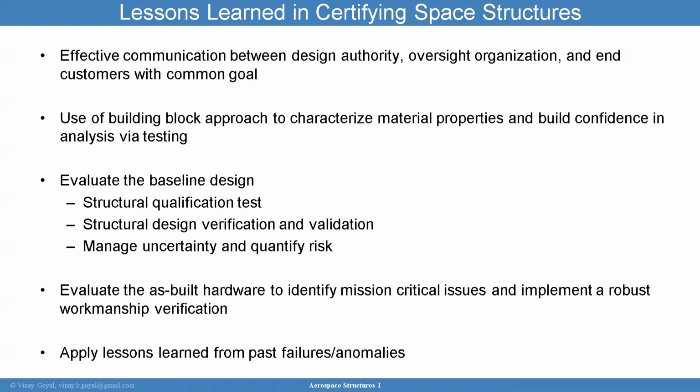What that means is that you went through a design verification phase, but you want to make sure that the hardware as you built it is good to go. And to do that, we already covered some aspects of that, but we want to make sure that the as-built hardware has been properly verified through workmanship. That means doing a proof test, doing the NDE, or something like that.